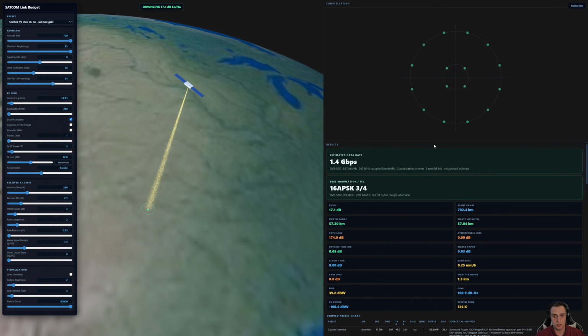So in this standard, they use amplitude phase shift keying. In these rings, these will be the amplitude of the signal, and then the angle around these circles will be the phase. We know from academic research that Starlink does it a little bit differently in the constellation, but they're still modulating the amplitude and phase of their signal. Now, what these communication standards do is that they change the modulation type and also the forward error correction based on that signal to noise ratio.